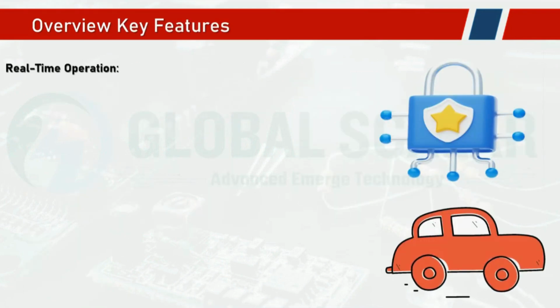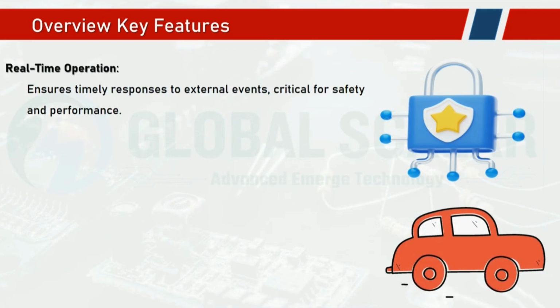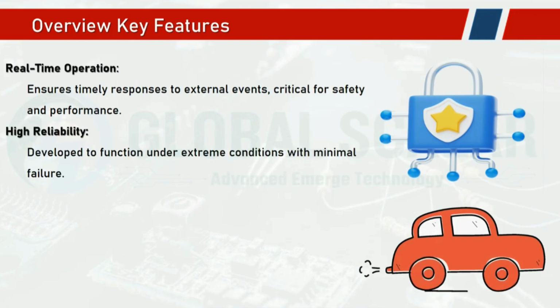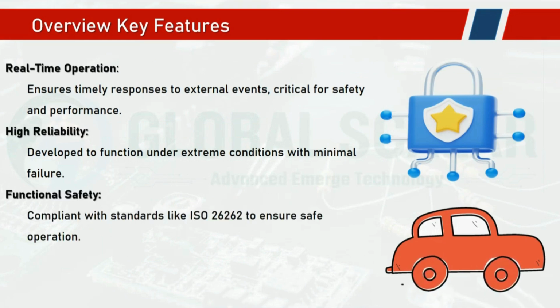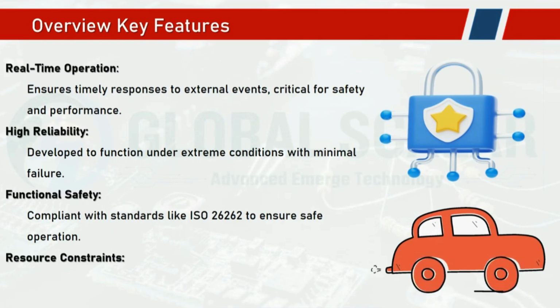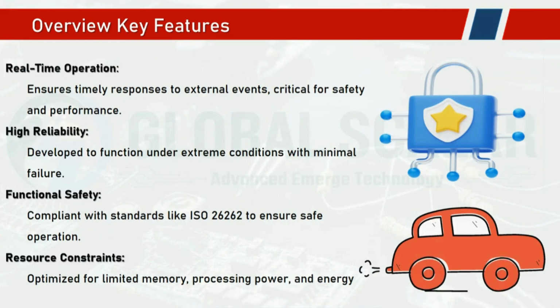The key features: real-time operation. We need to ensure that it responds in a timely manner to external events, which is critical for safety features and performance. High reliability: it is developed to function under various conditions with minimum failures. And functional safety: compliance with standards like ISO 26262, we need to ensure safe operations. And resource constraints: we need to optimize the limited memory, processing power, and energy.